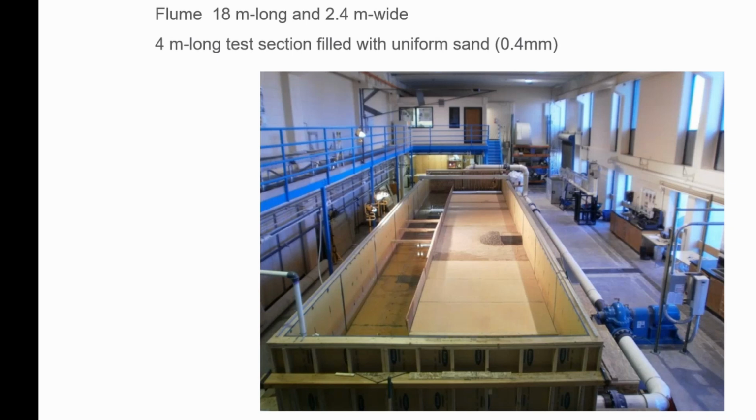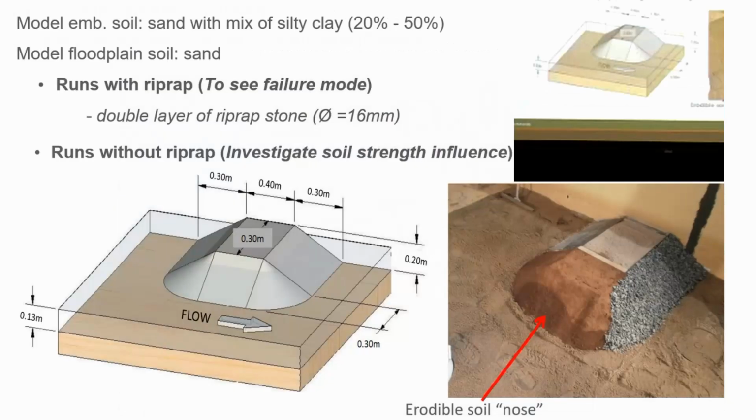And so we did a series of experiments in Wyoming where we had an abutment, and these are the dimensions of the abutment, and at the tip we had an erodible nose. We used sand, and we used sand mixed with silt, and we compacted it at the right moisture content. So it's more of a geomechanics problem, again, than a hydraulics problem. The rest of the abutment we modeled as rigid, and we coated the abutment with rock riprap, and we did experiments without any riprap as well.